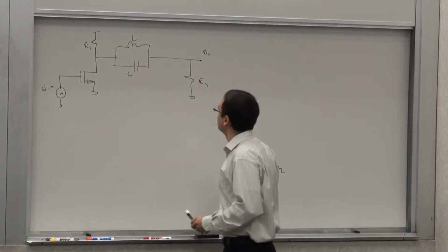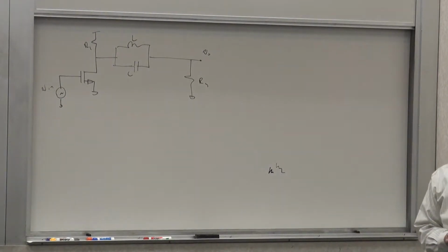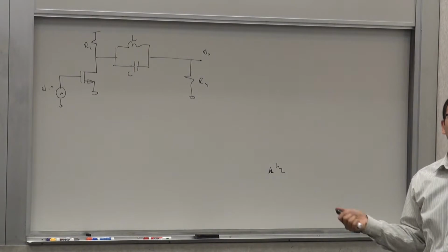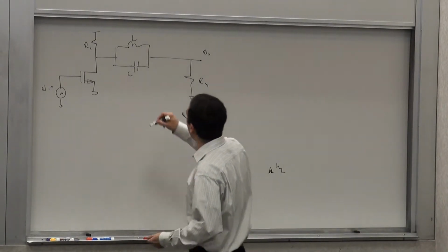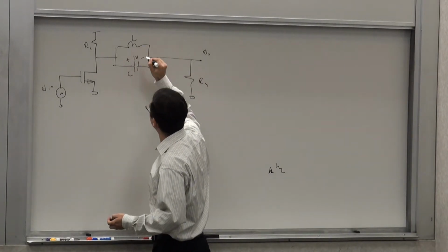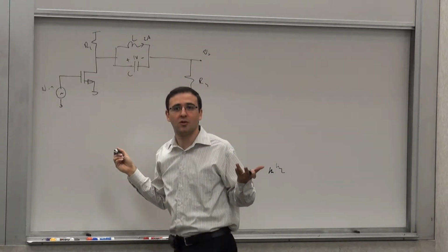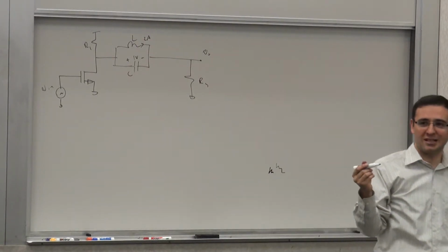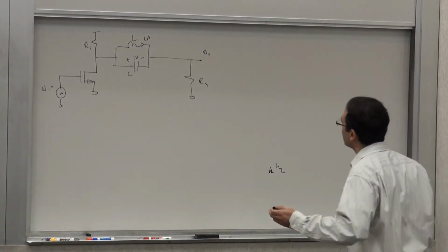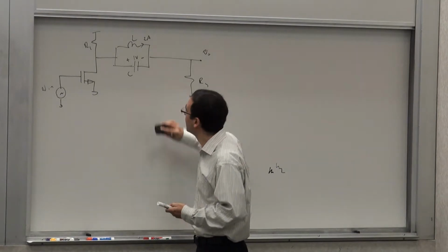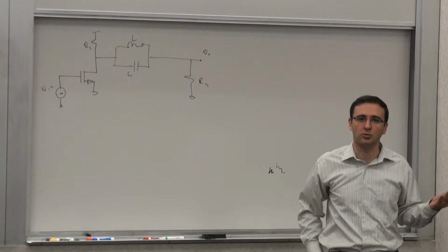Right. So, how many poles, how many zeros? Start with poles. How many independent initial conditions can I define? 2. I can set this voltage to be 1 volt and this current to be 2 amps, because for inductors you define currents. So I can define that current to be 2 amps and this voltage to be 1 volt and nothing happens. So I have 2 independent degrees of freedom. I have 2 poles.